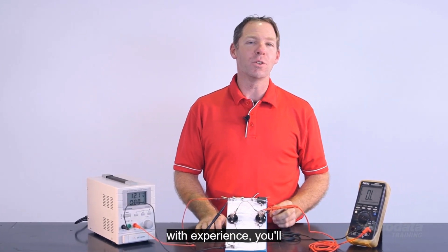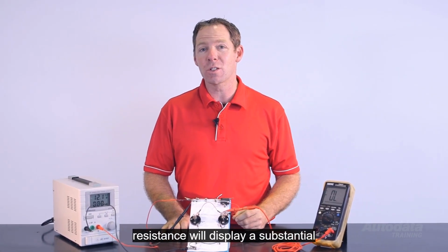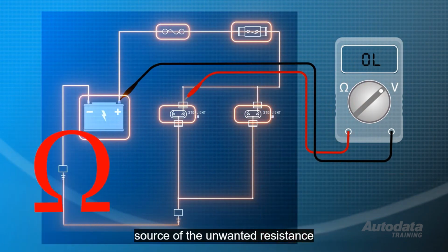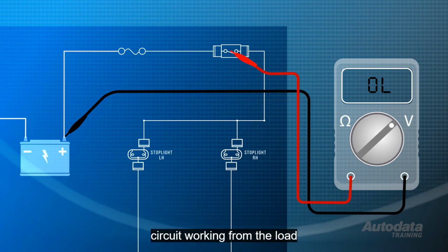With experience, you'll quickly learn that any problems associated with unwanted circuit resistance will display a substantial reading on the meter. With a substantial voltage drop over the entire circuit, we need to localise the source of the unwanted resistance. This is accomplished by repeating the test at each point in the circuit, working from the load back towards the battery.